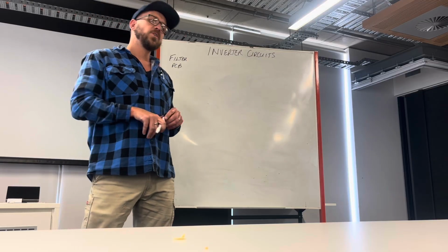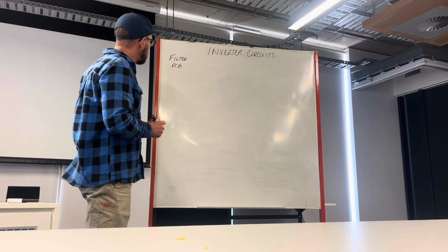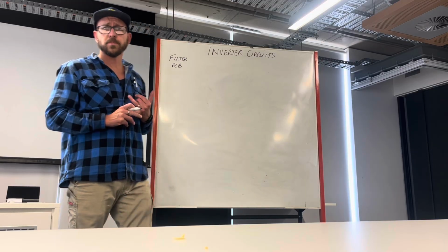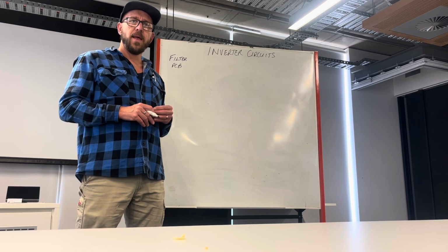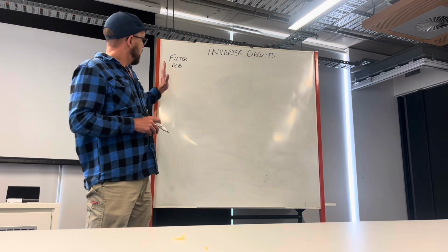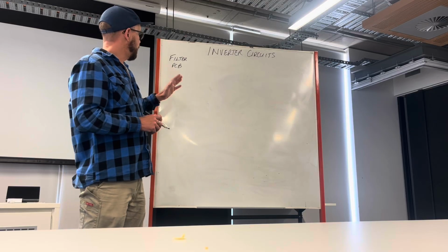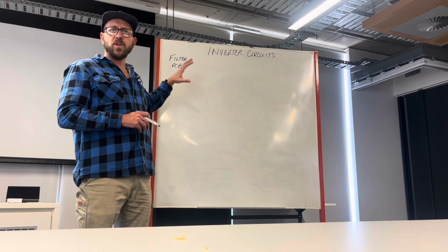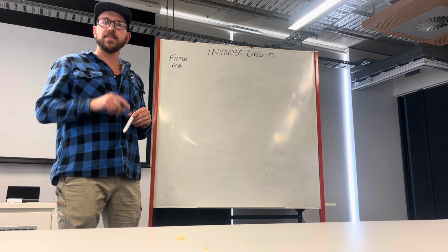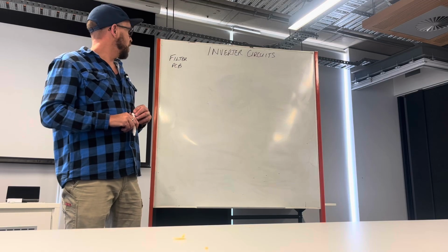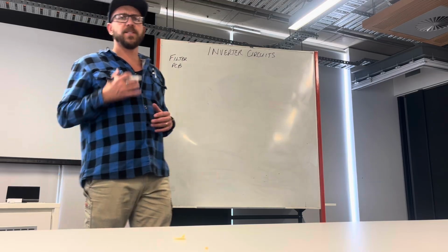Here in Australia that's generally 230 volts AC, 230 or 240 depending on the state. But our incoming power is getting filtered. It has noise filters on the board, surge arresters and varistors that can protect the rest of the componentry from any spikes, but also noise filters, so the inverter itself can generate some electrical noise. We don't want that interfering with the rest of our products in the home. So that's what the noise filters are for. So the filter board's really there to protect the rest of the equipment.